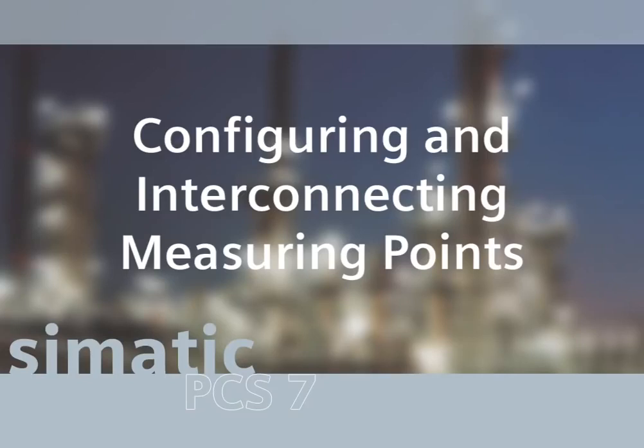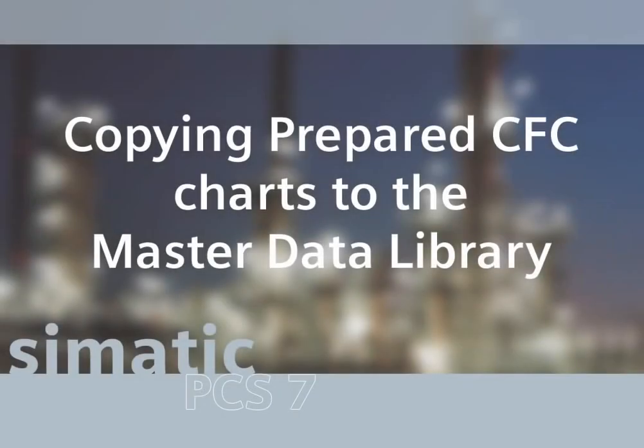The SIMATIC PCS7 library comes with standard templates, for example for motors, valves, and controllers. For the purposes of this exercise, we will make use of a customized library to show you how you can use your own company-specific templates. In the following steps, this library will be de-archived using the SIMATIC Manager. The individual CFC charts will be copied into the master data library.